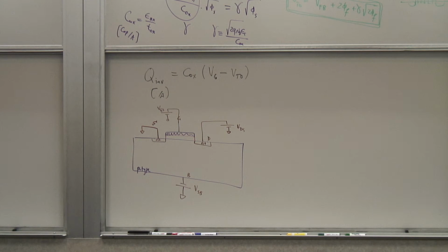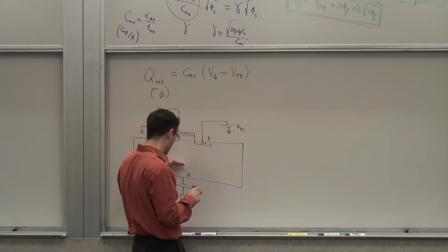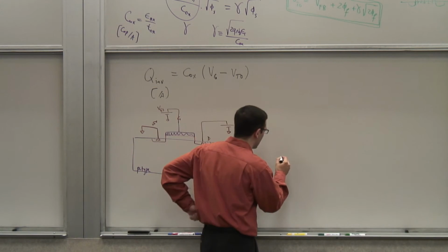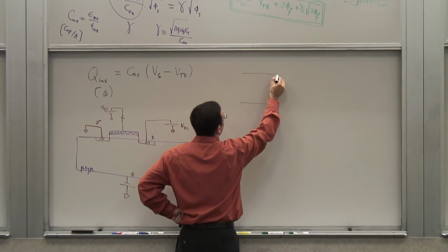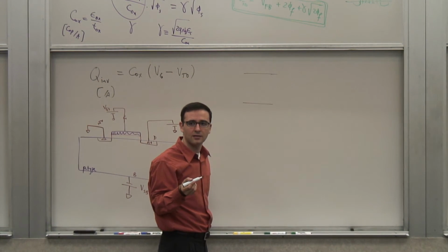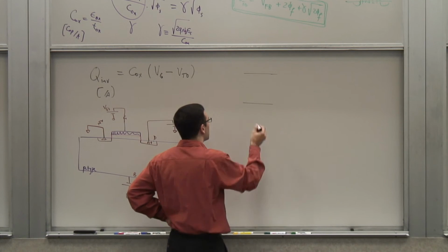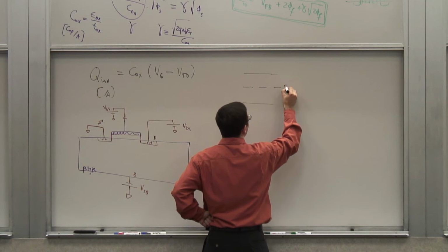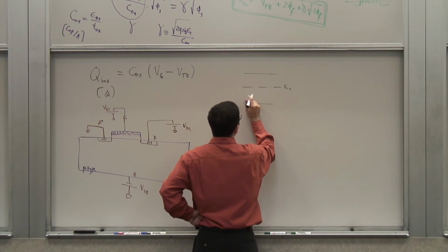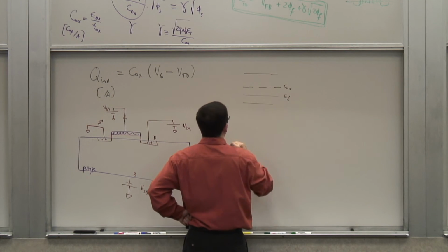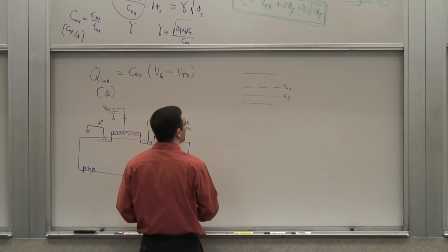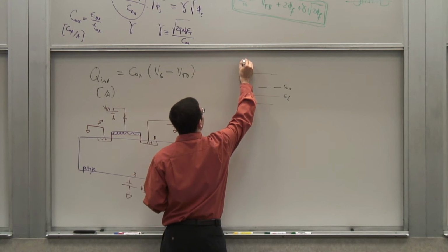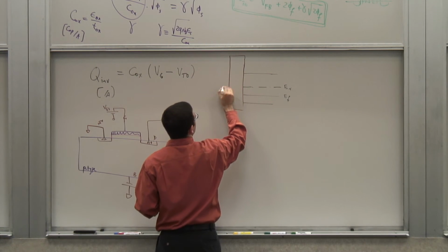Now, let me ask you a question. If I apply a positive voltage to this, let's look at the energy band diagram for the P-type bulk quickly and see how it behaves, right? So one of the things is that I know it's a P-type semiconductor. So is EF above or below EI? Below, right? So if this is EI, this is EF originally. Now I am putting it next to the oxide, and let's say under flat band condition it kind of looks like that.